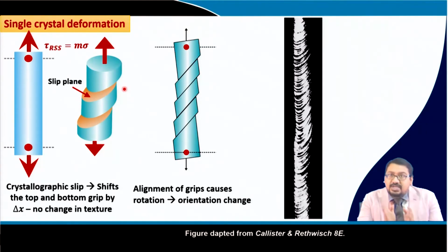So, the theta, that is the angle between the slip direction and the loading direction, decreases, whereas the angle zeta of the orientation, the smallest angle of the slip plane with respect to the loading direction, also starts to decrease, and therefore, the angle phi, the angle between the normal to the slip plane and the loading direction, starts to increase.